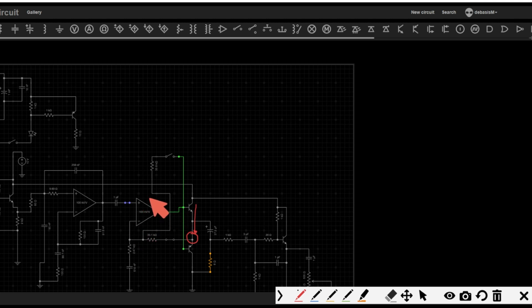So this op amp will do everything to maintain this voltage in such a way that this A voltage and this B voltage are equal. Because you have a feedback from here, the op amp indirectly knows what is happening here and will change the voltage here. It directly manipulates this voltage so that A equals B. So indirectly this op amp will try to minimize that distortion.